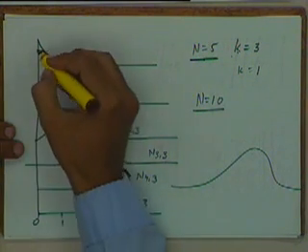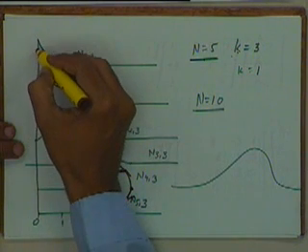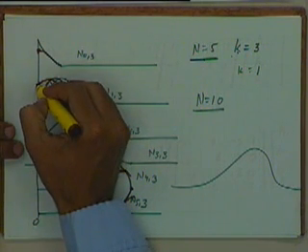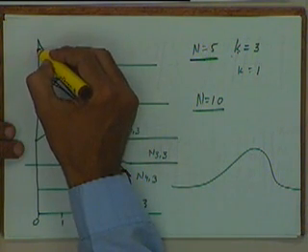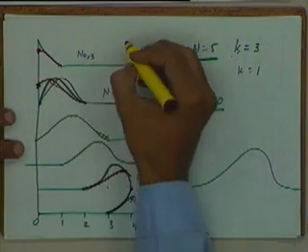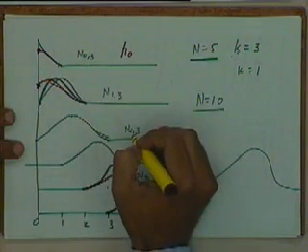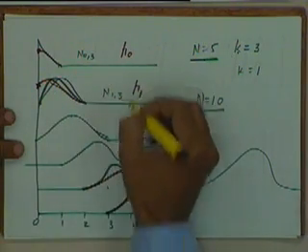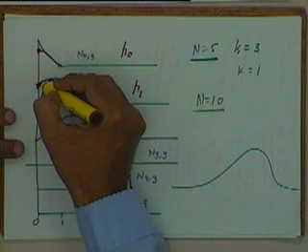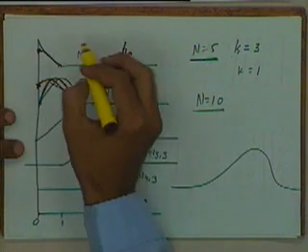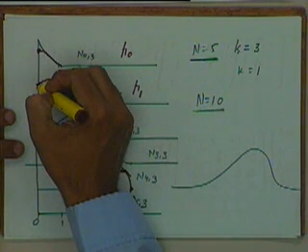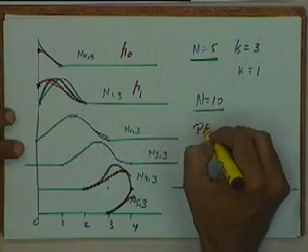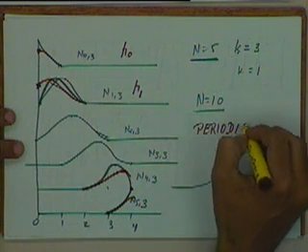If I do that, then at the starting point my curve will be a combination of this point and this point, because this is the weightage to be given to the point P0, and this is the weightage to be given to the point P1. I am giving a non-zero weightage to both these points. So the curve will start at some point which will be a combination of P0 and P1. Such curves are referred to as periodic curves, periodic B-spline curves.